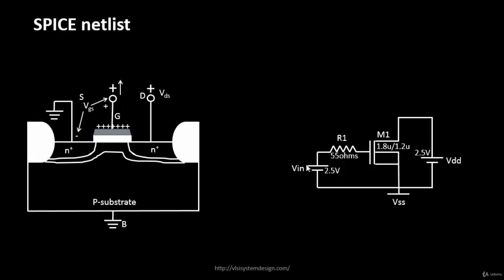Moving on, let's say you have this voltage source. From this point you just keep on moving, and there is no obstruction till VSS, in fact till this point. So this forms the second node. Once you go to this power supply voltage, from this point till this point there is no obstruction, so this forms your third node, and so on. So the first step is to define the nodes, so that we define the components between those nodes. Let's look into that.